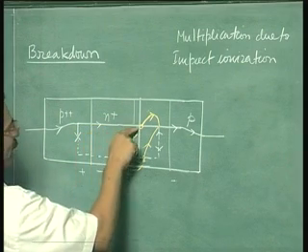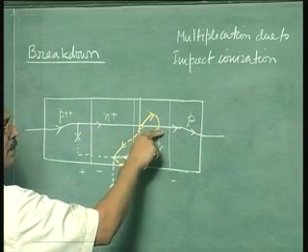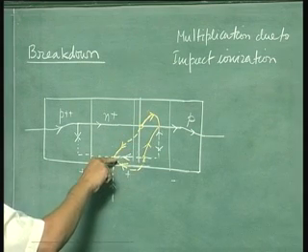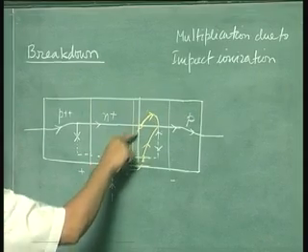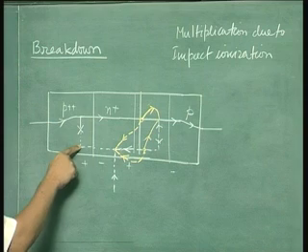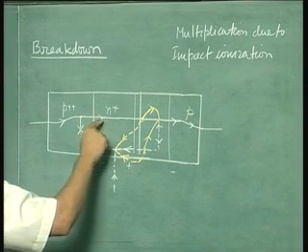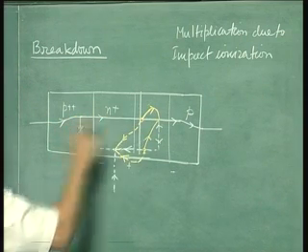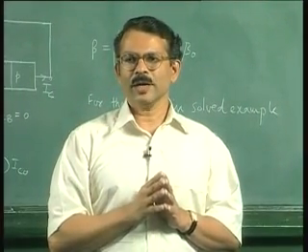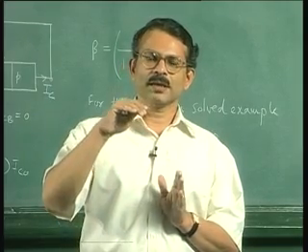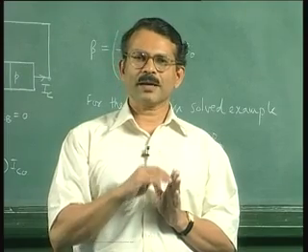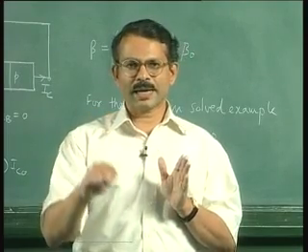So therefore the current that is moving in here is increasing, and this increasing current is further getting multiplied, giving rise to more electron hole pairs, and these electrons again come back to the emitter and increase the whole current in turn. So you see there is what is called a positive feedback. Increasing current giving rise to more current, which further gives rise to more current, and so on. So there is a feedback from emitter to collector and collector to emitter.